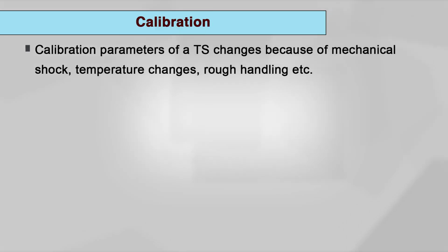In the last part, we discuss errors in the total station. The total station should be in permanent adjustment before using it for observation, but this is seldom achieved in practice and gives rise to instrument error. It should be ensured through regular monitoring of instrument error. It is important to determine the magnitude of the error and correct it. Instrumental error can be measured and corrected using electronic calibration. First we will discuss the calibration.